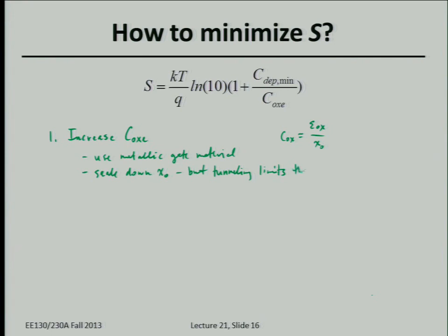So this is on the order of, depending on how much current you can tolerate in your gate, definitely going to be greater than 1 nanometer. So you cannot scale the silicon dioxide layer to be thinner than a nanometer. Otherwise, you'll just get too much gate leakage current. Right? In a MOSFET, ideally, you don't have current flowing between the gate and the channel. Okay, so what's another thing that the industry has done?